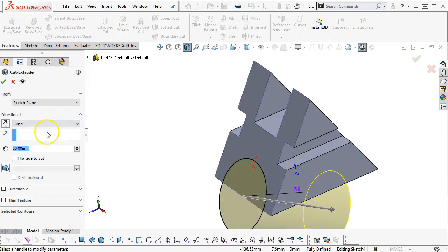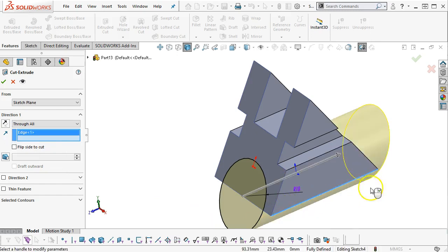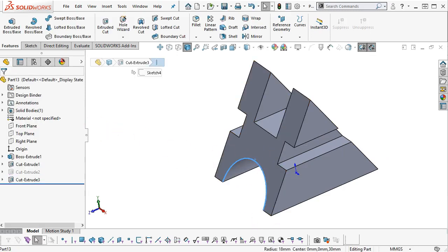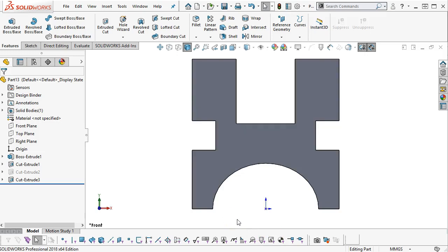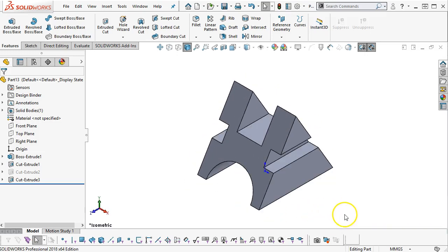But if we do an extrude cut and tell it through all, another box that we kind of jump over quite often is direction of extrusion. I'm going to pick that leading edge so that it brings that geometry through. Then now instead of having an arc length, I end up with a radius of 18, but looking at it on end, I have an ellipse. All right, so one of those two solutions is going to play out. I think the cylinder in most cases will prevail, so cut extrude 2.